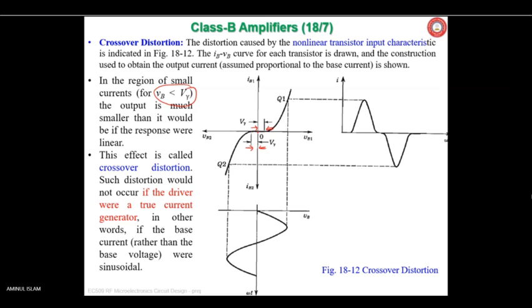See here, till this point you don't have IB. After that, it's a kind of diode characteristic. Are you seeing this one? You'll see the diode characteristic also like this. Until its cut-in voltage of 0.7 volt is crossed, appreciable current will not be there. Of course, if you expand this portion, you will get a little current, but it is very negligible.